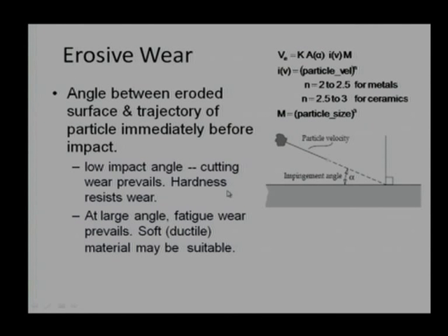But in this case, the shape of the particle will affect the wear rate. It will try to abrade the surface, it will try to cut the surface, it will work as a cutting tool. So particle shape will matter in that case, and to resist the wear, to reduce the wear rate, the hardness of the component needs to be higher.